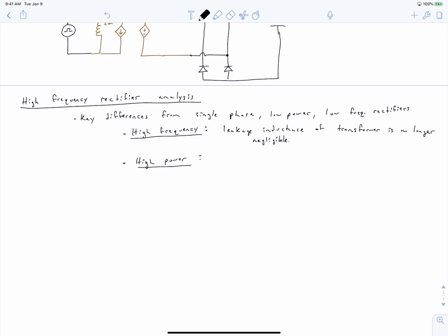very low. In the low frequency transformers, we would actually increase our coil resistance as a means to prevent short circuit currents. In this case, we're doing everything we can to eliminate or greatly minimize the resistance we see in our coil winding, which means that in our equivalent circuit model, we can typically neglect the series resistance of the coil.